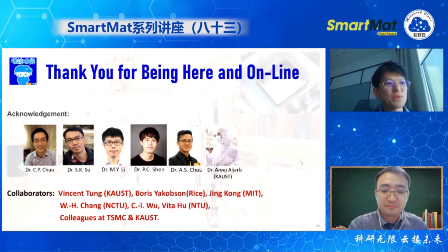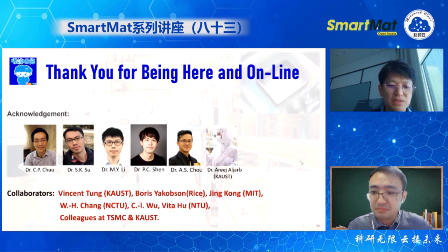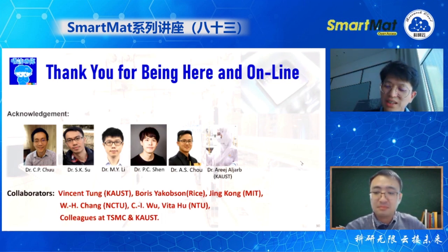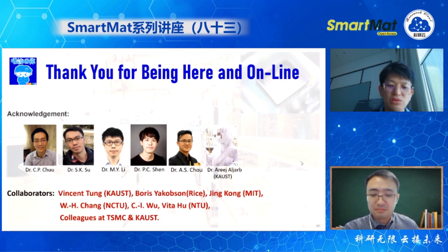Yeah, this is a tough question for me because I don't work on graphene. I did have some graphene experience, but I didn't really make it to device level, so I prefer not to answer too much on that. But graphene does not have enough gap. So in terms of high-performance digital electronics, probably there's no hope, because for digital electronics you need enough bandgap to have enough on-off ratio.